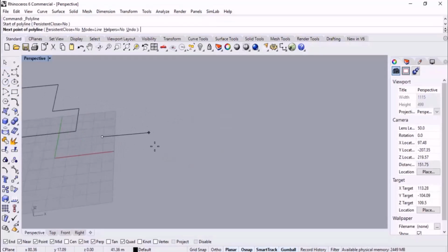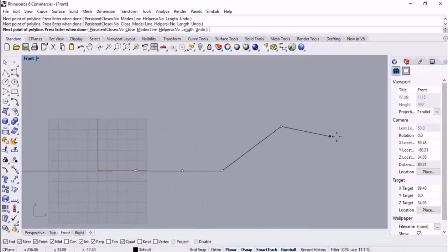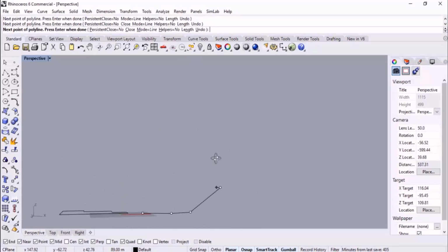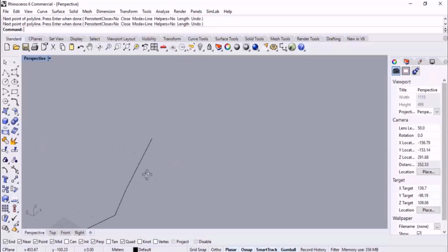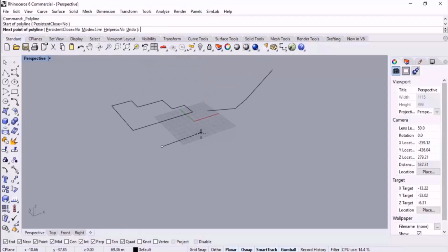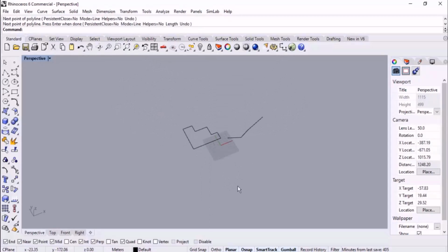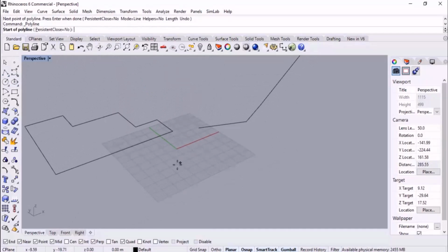However, instead of pressing down the control button, we can just switch the view. As you can see in front view, it gives us access to sketch the line perpendicular to the plane. However, holding down Control has its own application: you can click to sketch a line, and then hold down or press down the Control button. Then you can move the mouse to specify the position of the point and then click to sketch it, like this. I got a question for you.